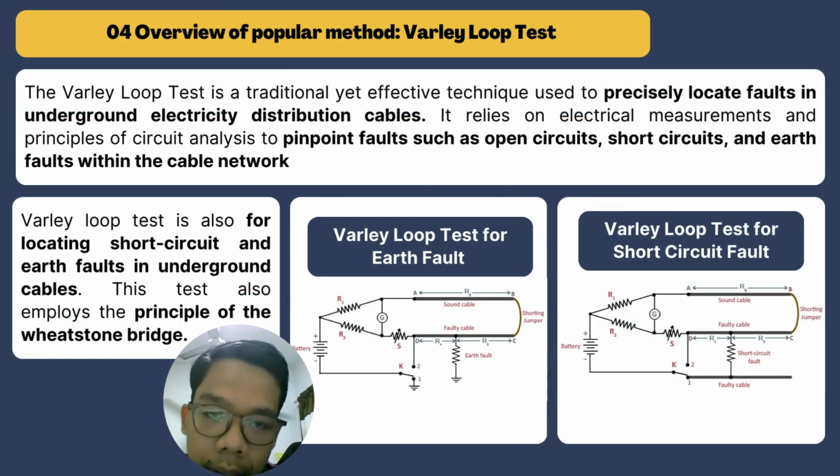So what is the Varley loop test? It is a traditional, effective technique used to precisely locate faults in underground electricity distribution cables. It relies on electrical measurement and principles of circuit analysis to pinpoint faults such as open circuit, short circuit, and earth faults within the cable network.